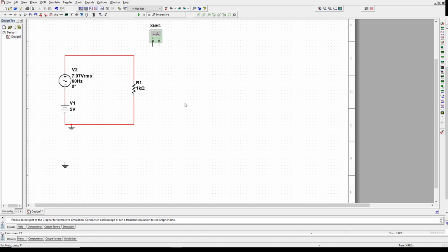Now let's connect the voltmeter. We're going to connect the voltmeter across the resistor, which means basically we're going to get whatever is between these 2 points. All right, and the resistor just completes the circuit. This is our load. Connect it here and connect it here. It's fine.